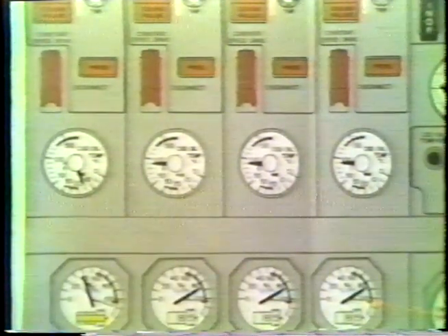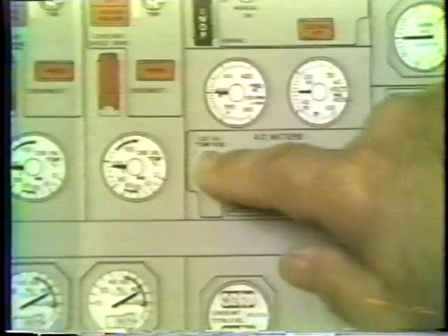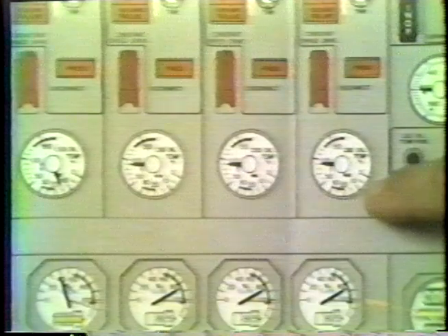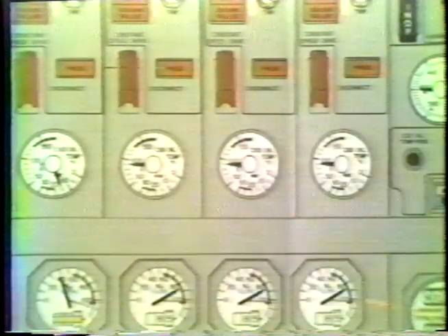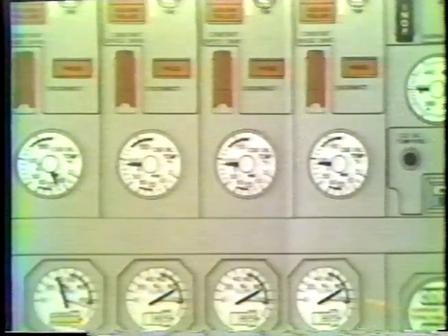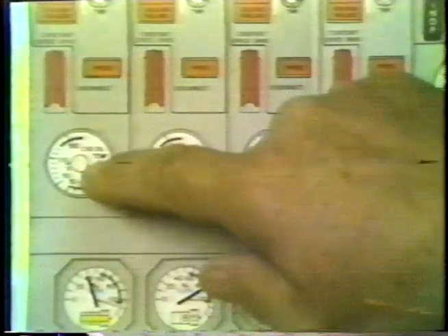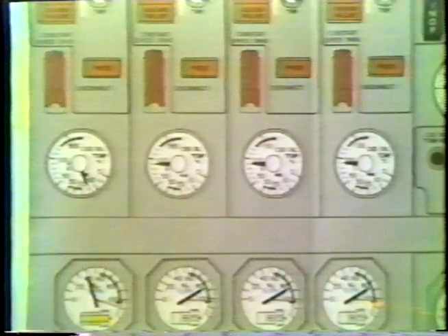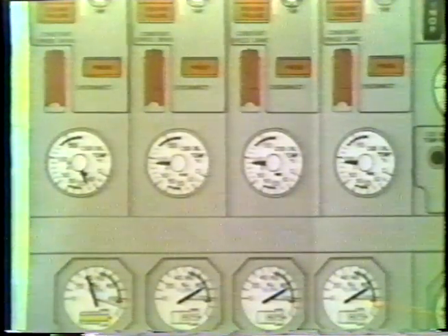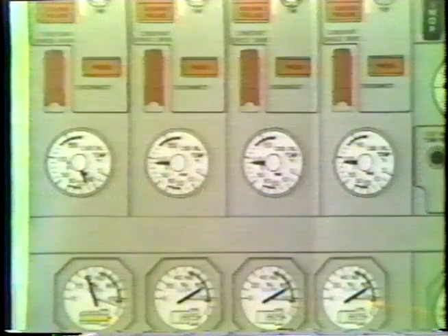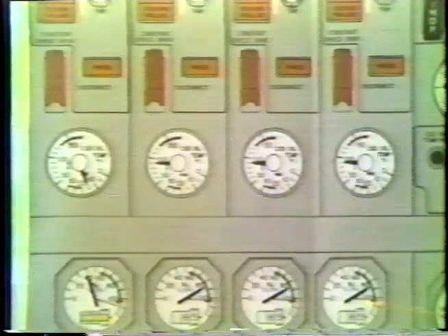If you wish to look at the rise temperature, there is a CSD temp rise button, which upon depressing the button causes all 4 gauges to look at the rise portion and read on the lower portion of the scale. Now the 2 parts of the scale represent 2 different types of operation of the CSD. The out temperature indicates the ability of the air, which uses fan air, to cool the CSD oil. And it tells you how well that's working.